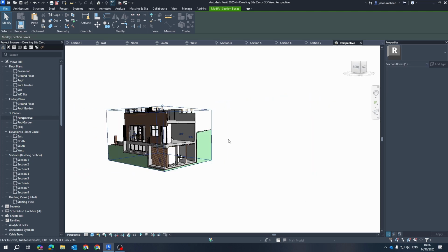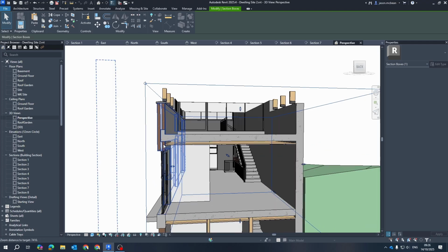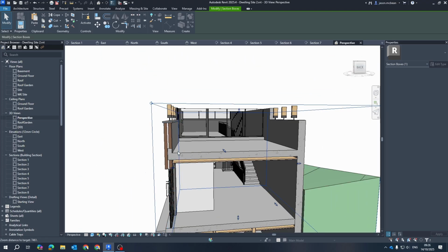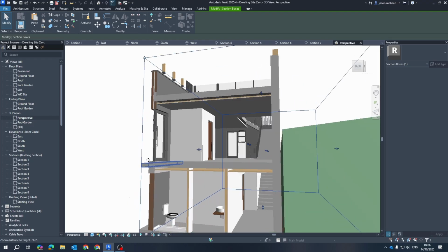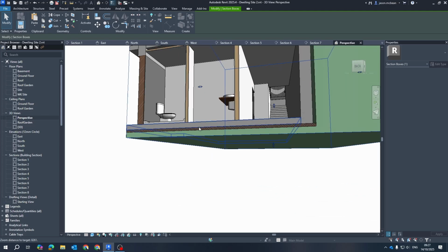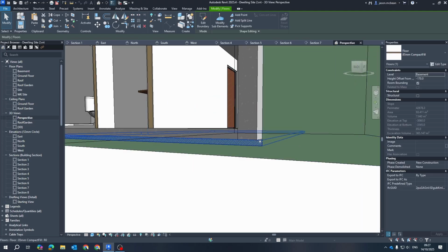I'm just going to show you through the building, and you can see I've put upstand beams. So I've put upstand beams where these columns will connect to, just to add some support. So this is a typical workflow, something that you have to consider. You can see that Revit doesn't always connect things. You have to sometimes go and join things manually. Just as a word of warning, I've also used a floor type.